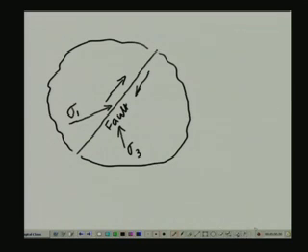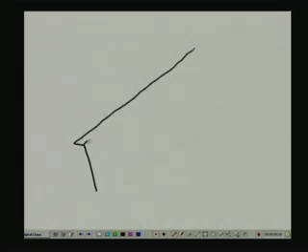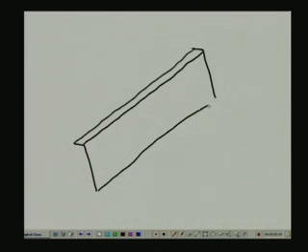Now let's say we have got a dam which is very long in comparison to its height, and in this particular case the strain in the direction perpendicular to any of the cross section, or in the direction of the dam axis, can be neglected.